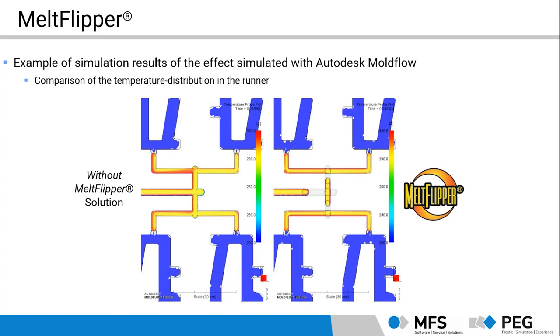You need a very, very fine mesh. So temperature increase, that is possible to simulate. What you cannot simulate is the degrading of the molecular chains. So this part of the effect is not possible to simulate, and so you will see this effect not that strong in simulation like you will maybe observe it in reality. This is important to know.